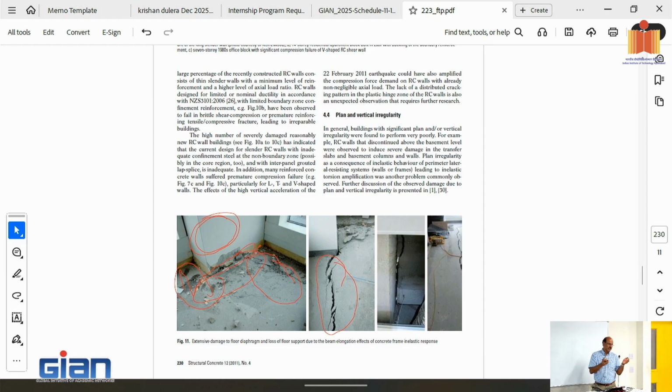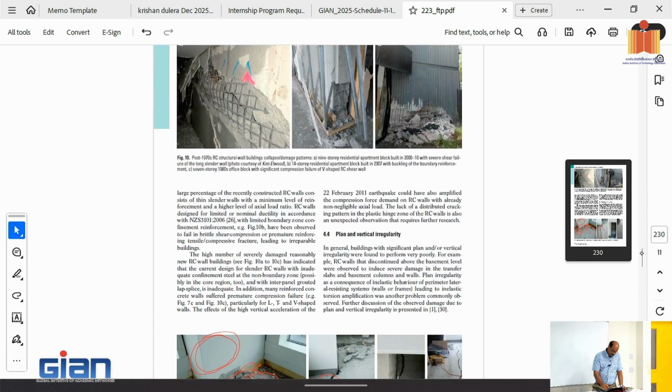But as I explained to you, those gaps are not unique to precast. If you have cast-in-place, if you have steel structure, they're deforming. Gaps have to open up somewhere, right? Otherwise, if it's a welded connection, it's going to just fracture. We've seen it in earthquakes as well. So the floor interaction has become more of a concern for precast structures. And that's something you see here.